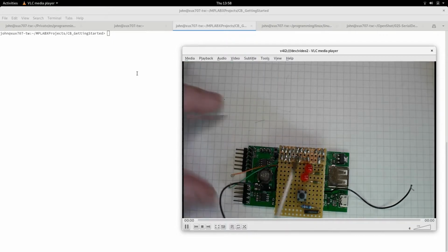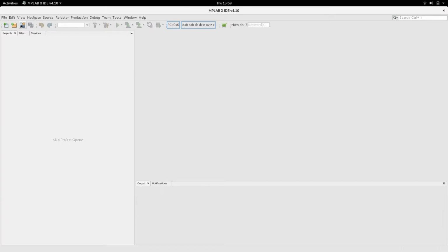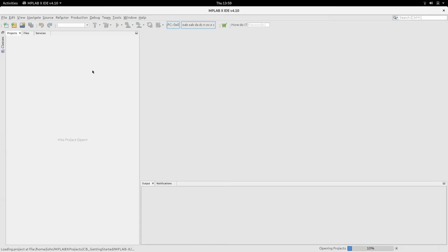Now the way I program, I throw printfs all over my code when I'm developing, check that everything comes out the way I'd expect it, and then remove them when a project is in production, it's been tested and you know it's working. You can strip down all those debug messages, so all the logging comes out of the code. So we're playing with this getting started project, and I'm going to add serial logging to that project.